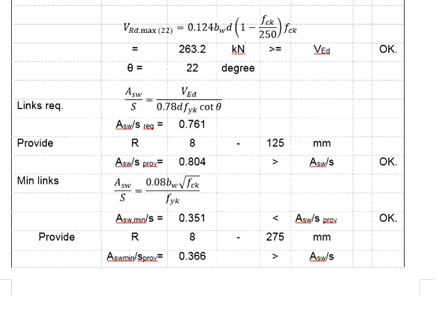You may adjust the spacing at intervals of 25 mm, as 25 mm represents 1 inch. In industry, the workers normally work with inches instead of SI units. Therefore, when you decide the spacing, you can adjust it by intervals of 25. For example, 100 mm, 125, 150, 175, and so on. Test the ratio with different spacing until you find a spacing with the ratio slightly greater than the required. You can still get the R8 125.